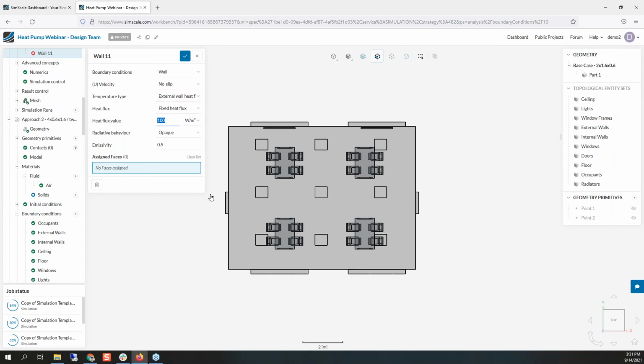So for example, you have 30 watt per meter square of heat generated by the radiators. This can also be set as a boundary condition. So this is on the pre-processing side of the power input. And on the post-processing, you can derive the temperature difference from the ambient condition, and the power can be easily calculated from there. I hope that answers your question.